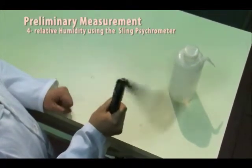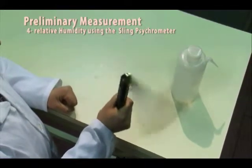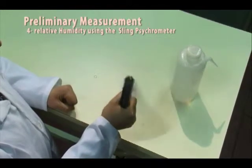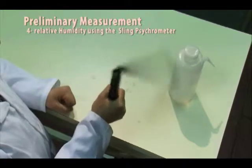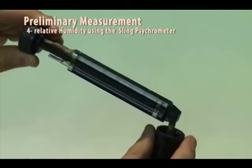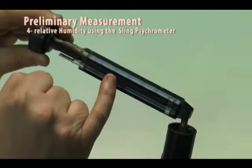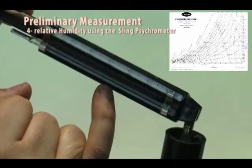The sling psychrometer is whirled around for about 1 to 1.5 minutes. After that, the temperatures of both thermometers are read. During the whirling, the water evaporates from the wick, cooling the wet bulb thermometer. The relative humidity can be determined using the measured dry and wet bulb temperatures and the psychrometric chart.